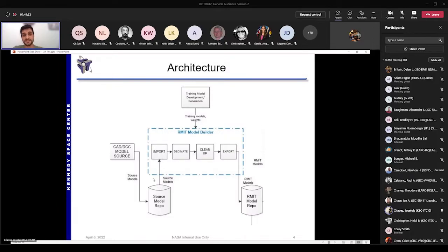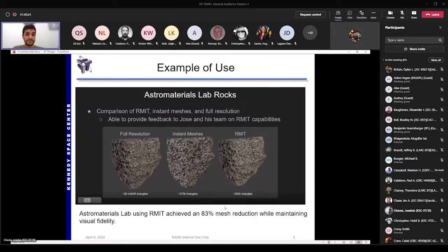We do use what's called Datasmith. Datasmith is a pretty powerful importer that Unreal uses. We essentially utilize that engine in the background to expand our file types. It's really hard creating file parsers for different file types that continuously change. So we let Datasmith handle the heavy lifting when Blender cannot. So we'll import it. People typically decimate, use the different cleanup functions, and then export that to whatever type of repository or the next engine that they're going to be utilizing these assets in.